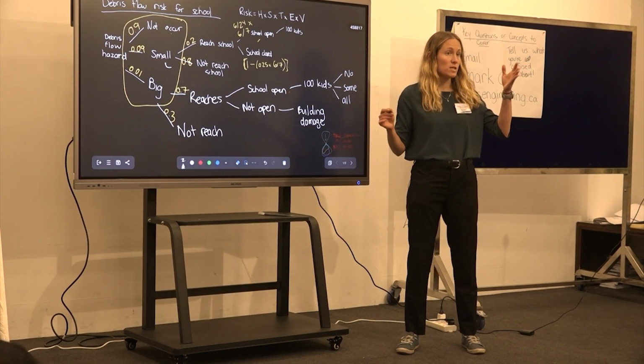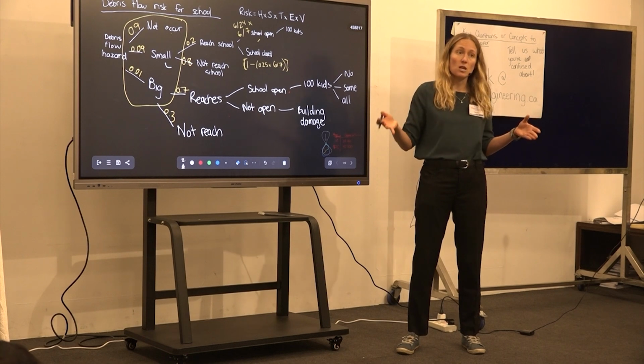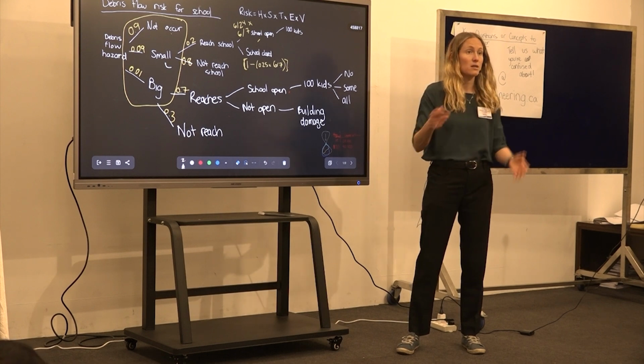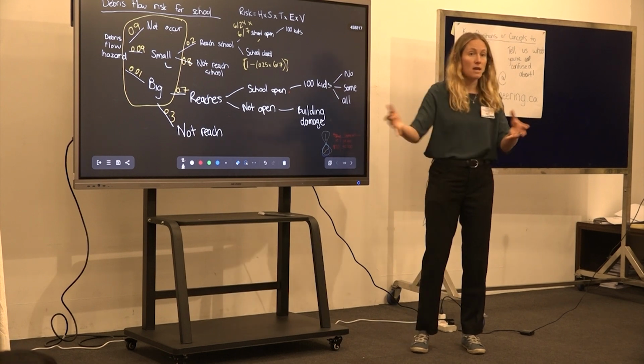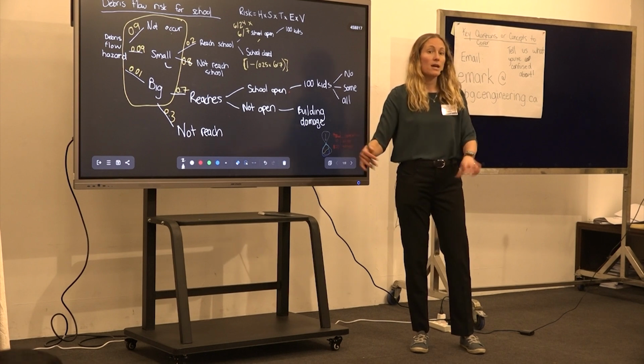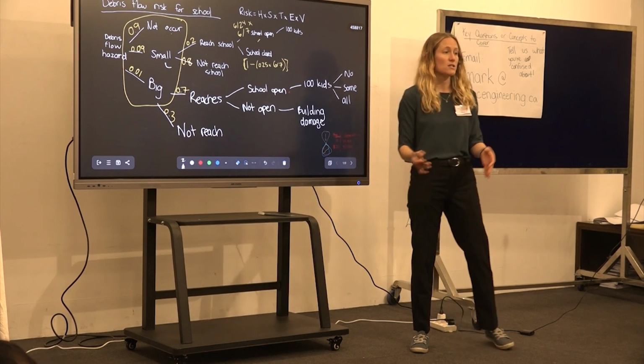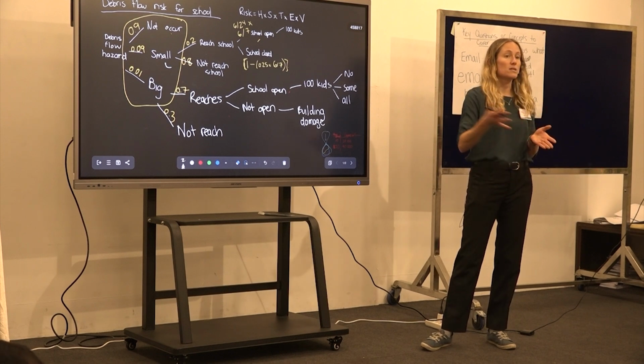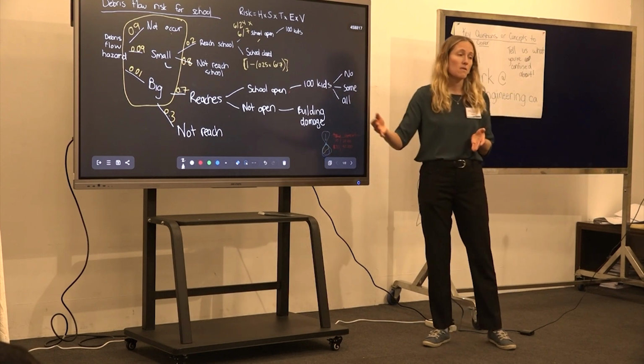Someone in the audience pointed out that a type of fragility curve is a depth damage curve. And so you can have depth damage curves that correlate a certain flow depth to damage in the building and infrastructure. You can have the same kind of thing that says for a certain depth or velocity or flow intensity, what is the likelihood of fatality in the building?